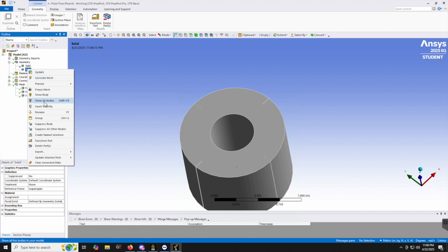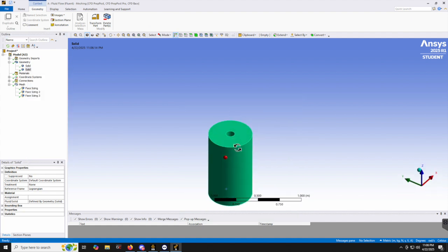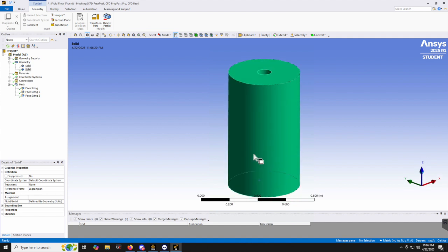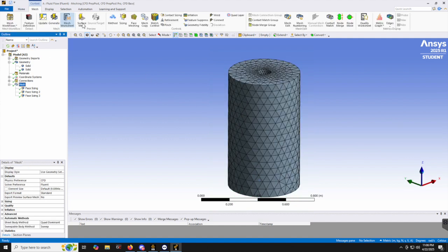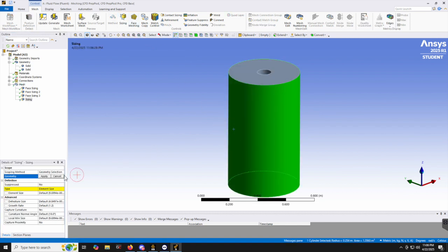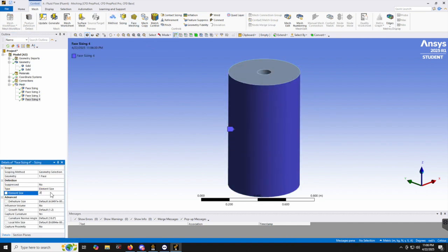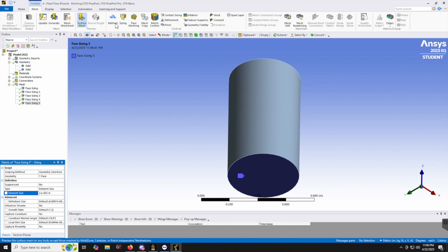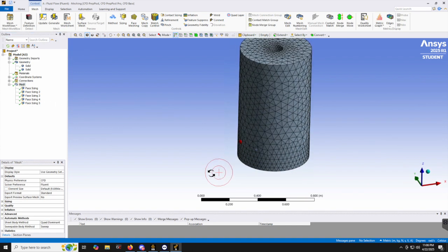We're going to do the same thing on the inside region because we want the meshes to be roughly similar between the two interfaces. So I will go into mesh, do a sizing on this face of 0.05 meters, and another sizing on the bottom face, like the outer region, 0.03 meters. We will generate this and see that it looks similar to our outer region.